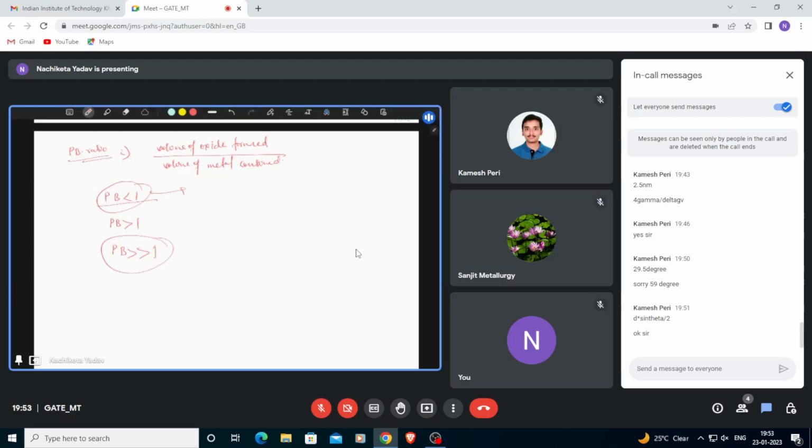So it is like brittle type of oxide you will get, right? Tensile stress in oxide film. There will be a tensile stress in oxide film in this condition. And this is just opposite of that. We can say compressive stress. And this is too much compressive stress in oxide film, meaning oxide will crack anyway.